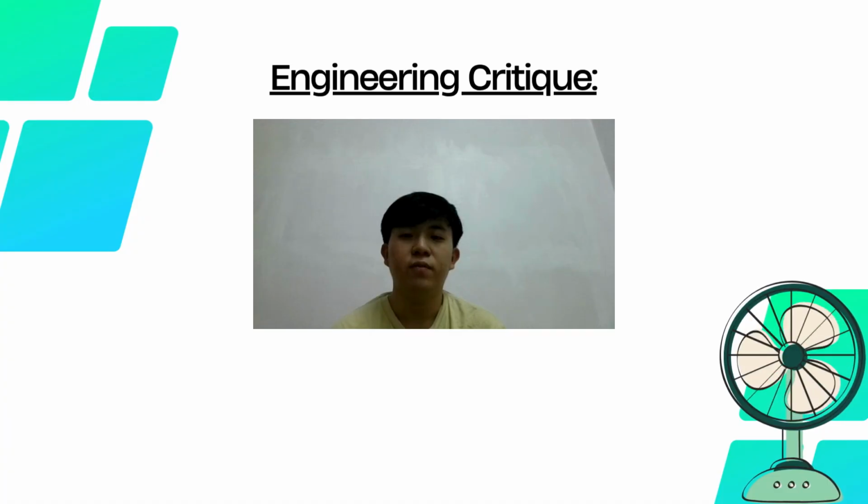From the safety perspective, the estimated braking force is relatively small compared with the structural capability of a household stand fan, so the system is considered mechanically safe under normal operation. As an improvement, I propose using lower-friction bearings and optimizing blade geometry to reduce energy loss and improve efficiency while minimizing impulsive loading force.